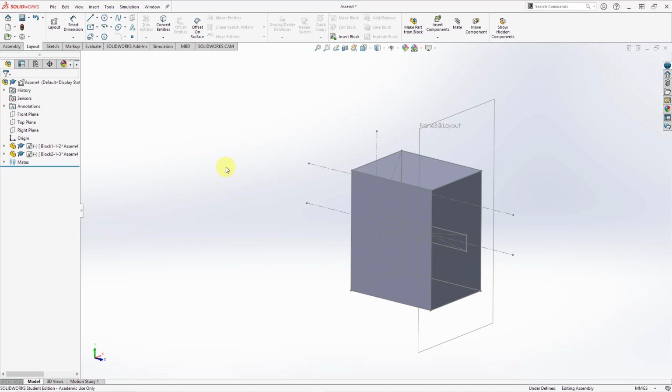And so that is sort of like the kind of equivalent of the skeleton in Creo Parametric. Now, honestly, from what I hear, a lot of people don't really use this because it is kind of messy, and you can see how all of a sudden I got over constrained with just a very simple kind of sketch of essentially a few different rectangles on different planes. But anyhow, that is how you can use layouts in SolidWorks as part of the top-down design process.